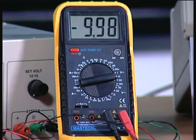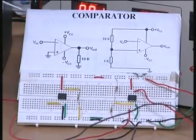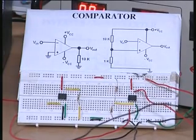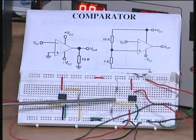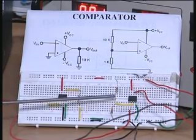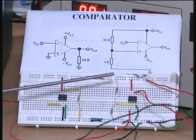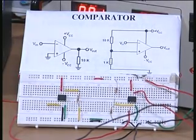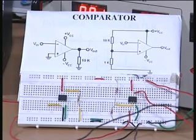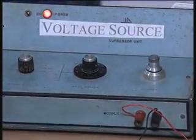So this shows that the comparator is capable of detecting voltages within the range of 1.2 volts plus or minus 120 microvolt on either side, as I was mentioning to you, and therefore it can be used to compare two different voltages. Now what I am going to quickly do is modify the circuit and go to the second circuit.